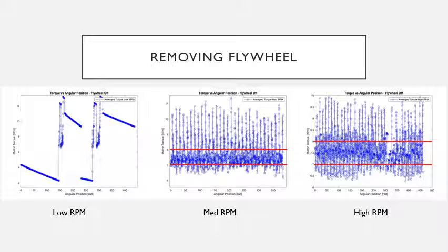This might be attributed to a higher vibration of the engine and/or to the breaking down of modeling assumptions in this mode of operation. Looking at the assumptions that were made, a potential cause for error is the piston work being assumed to be zero. This assumption holds true for high flywheel mass or large ranges of numerical integration, but with the flywheel mass removed, the assumption is not valid and the model seems to begin to break down.